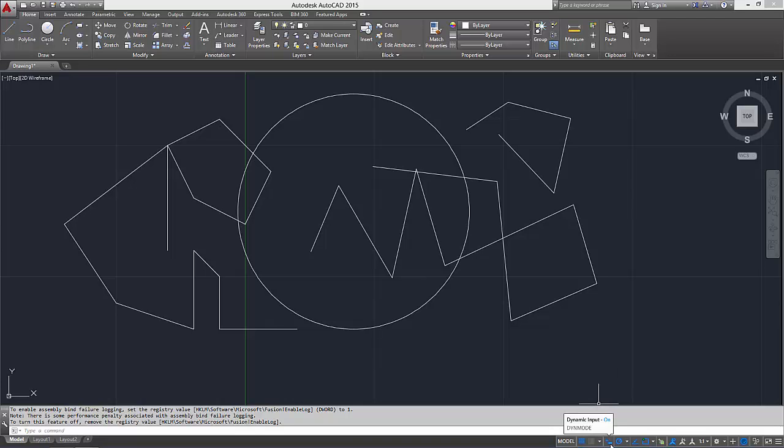I'm not going to go through all of these, but this one really is important. Dynamic input, we need to have that on. We also need to have polar tracking, and you can click on this and set the angles for which you set track lines. At the moment it's set for 90, 180, 270 and 0. So if I clicked on the line tool and started somewhere, I get a line going vertically up, 180, 0 and 270. If I change the settings to every 15 degrees, I'm going to get a track line coming out every 15 degrees, and I can track along these lines knowing full well that it is an accurate 15 degree angle.